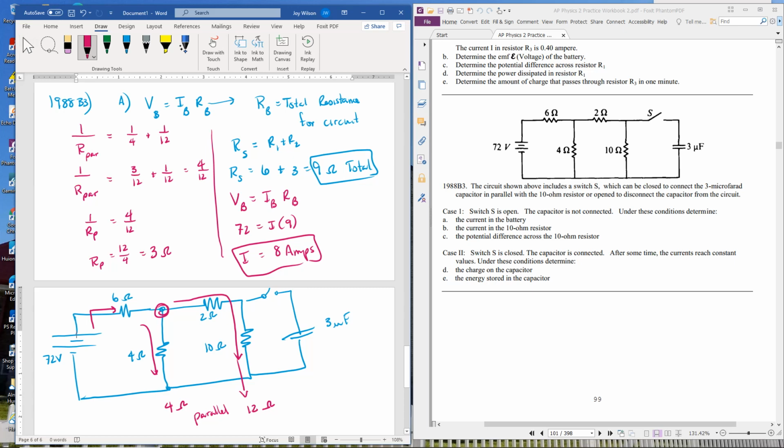So once again, what did I have to do? In essence, and I'm going to walk this back a little bit with you, this circuit acts like you have a battery, a 6 ohm, and over here you have a 9. So it acts like there's a 6 and a 3. The parallel piece acts like a 3 ohm resistor. So those two pieces together are what adds up to that. And so when we do our total resistance, it's a series at the end because you have battery, 6 ohm resistor, and then into the parallel piece only gives you 3 ohms of resistance.